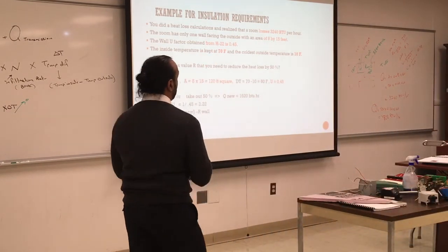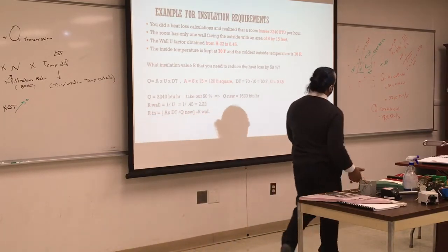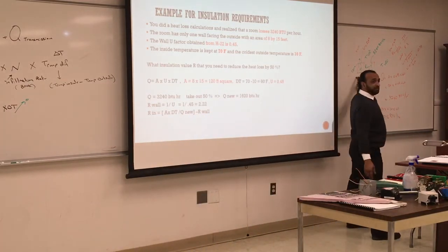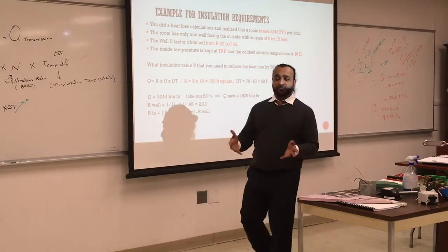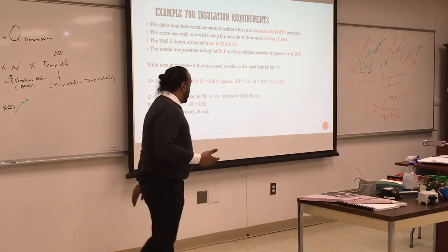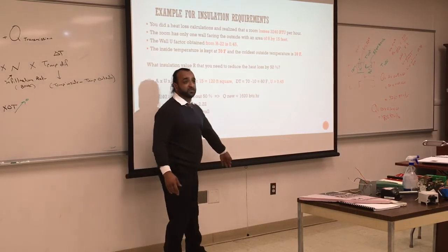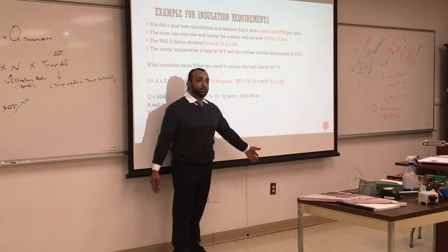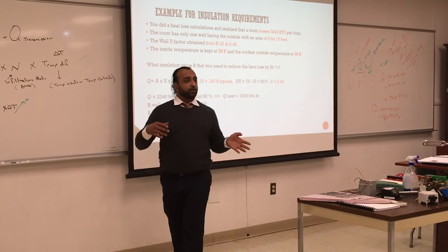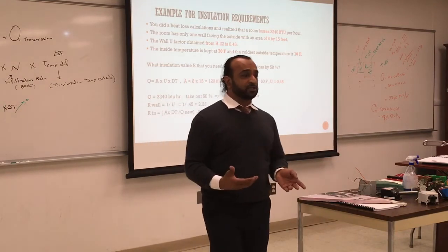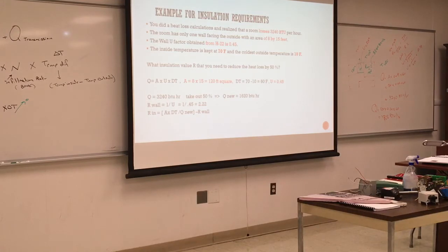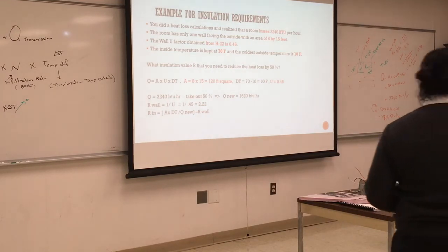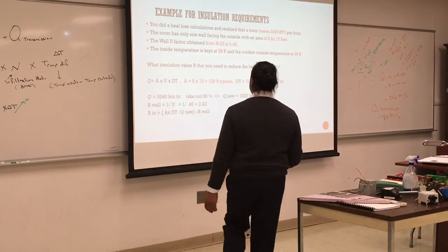Okay, but we can counteract transmission by adding insulation. We can counteract infiltration by retrofitting those areas. Some of the areas where you lose a lot of heat is sockets, by the way, outlets. There's no insulation behind it, so we want to make sure that it's completely sealed. My living room window is leaking air like crazy. In the cold, when it's windy, I can feel the cold air coming in. So probably I have to go and caulk it.